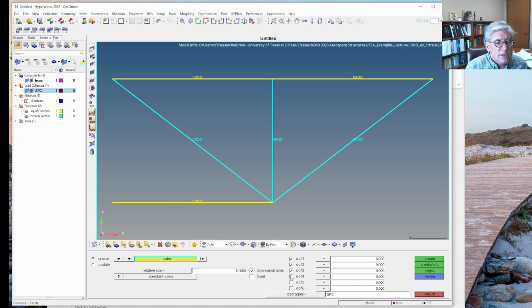And you can see here I've got buttons that allow me to constrain any of the degrees of freedom that I want. You can unconstrain those. Like, for example, if I do this, I'm just constraining the translation in the X direction to be 1. You could set it to a non-zero value. You could make it move an inch. Okay? So we won't do that necessarily, right? But we're first going to fully fix this upper left node, and they're all going to be set to 0. Right, so that's what I did here.